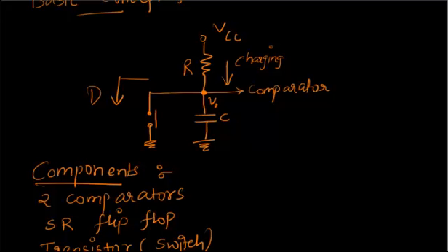It essentially consists of a power supply and a capacitor which has to be charged. Now this part of the circuit has just got a switch, SW. When the switch is open, that is when there is no contact, this will charge this capacitor. All the supply will come here and this capacitor will charge up to the maximum potential. So it will be something like this.